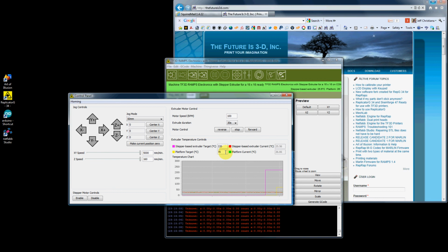150 plus Celsius. Down below here, you'll see what you've set your temperature to is the purple. The platform temperature is your yellow. These lines here down below, the red and the green, will slowly, gradually rise up to meet this set temperature. So this is a good way to troubleshoot if you have any intermittent heater issues, any problem. It should be a nice smooth arc that arcs up and then gradually moves in, and it should hold its temperature between 2 to 3 degrees.